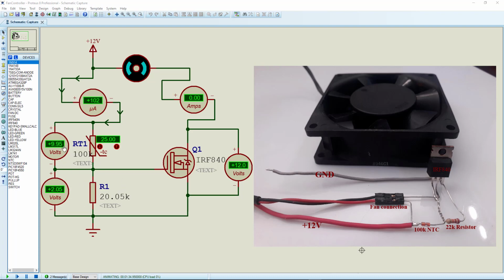And we have 10 volt dropping across the thermistor, NTC. Clearly, this 10 volt is the supply voltage minus the 2 volt dropping across the resistance R1. So here, basically, we have a voltage divider circuit, which illustrates Ohm's law. We can see that the current meter connected in this series circuit is reading 102 microamps of current at 25 degrees.